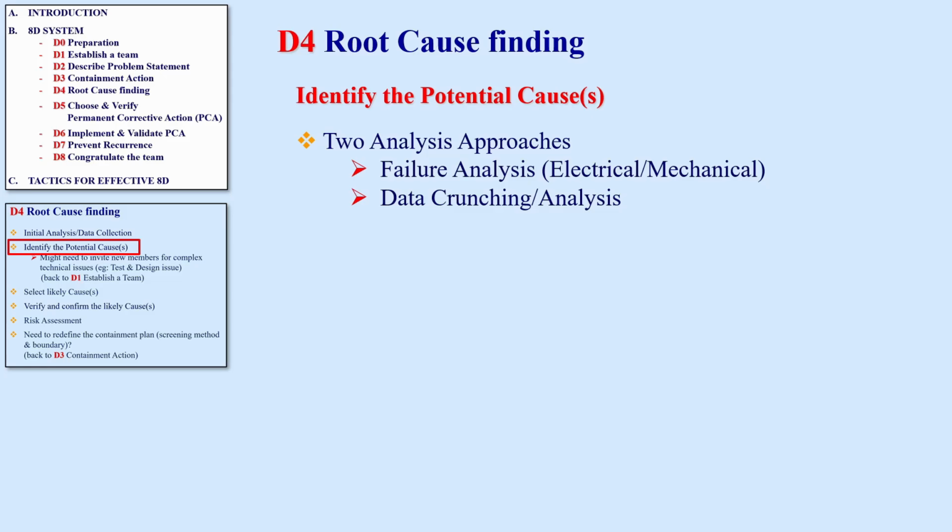Electrical failure analysis is through the understanding of circuit schematic, while mechanical failure analysis is through dimension-tolerant analysis, cross-section, Dye-and-Pry technique, etc. There are many statistical tools available for data analysis. Anyhow, this is beyond the scope of this training. When there is opportunity, I will develop a training video for this.